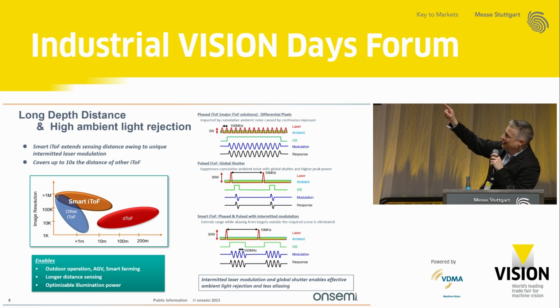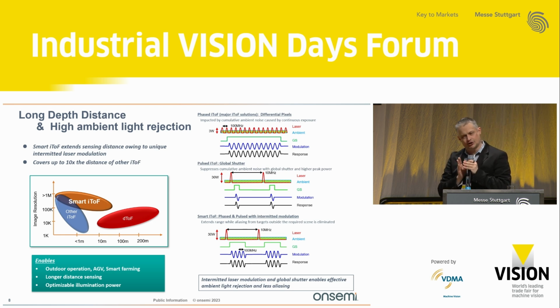So this is really the key to how you're able to image with depth, at far distances, and especially outdoors, because effectively the sensor is only exposing for a very short period of time. Also, for eye safety reasons, you don't want to burst that VCSEL at really high intensities for a long period of time. People may not be able to see the 940 nanometer, but it certainly can affect your sight.